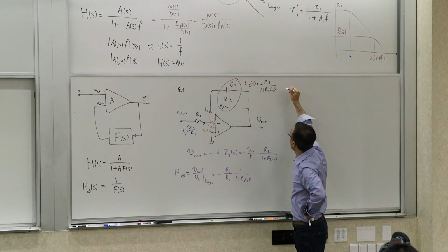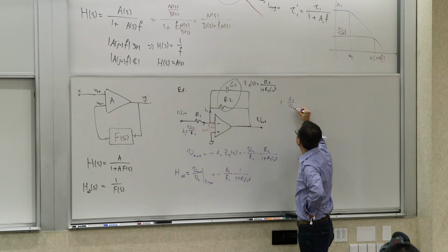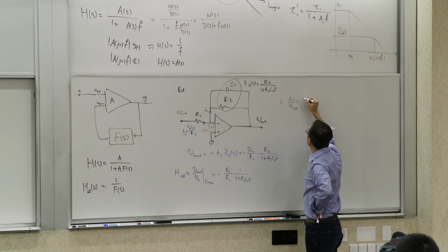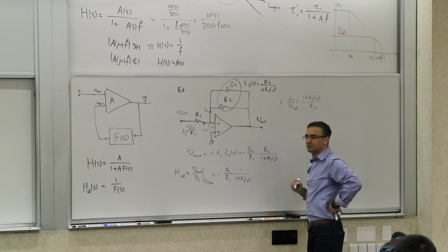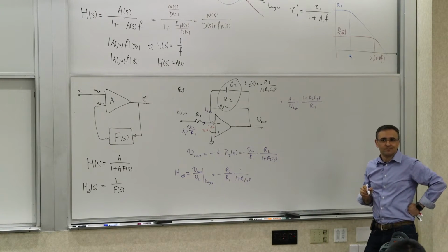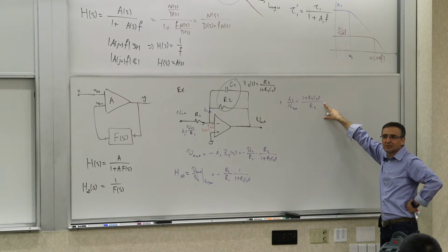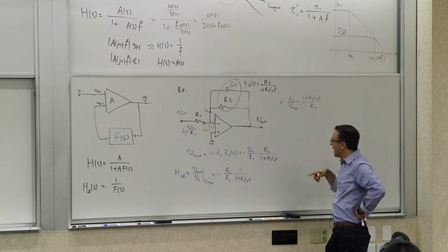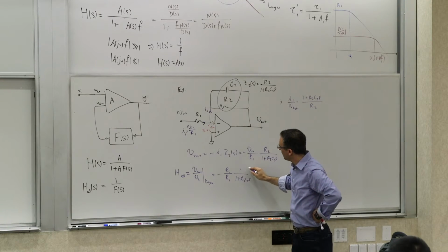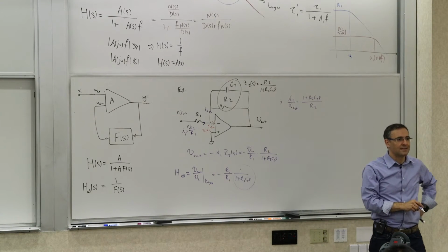And that transfer function is the opposite, right? So if the output is I1 over V out, it's going to be the inverse of that. So it's going to be 1 plus R2 C2 S over R2. So your feedback network had a 0. The transfer function of the feedback network was a 0, right? You have this capacitor here, and those things produce a 0. And then the feedback turned it into a pole. That 0 became a pole.